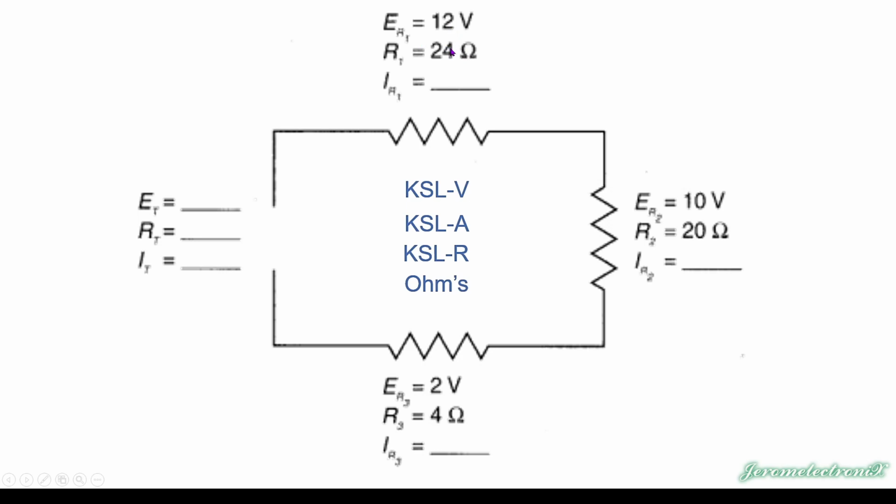Be careful. A lot of students look at this and say, oh, that's half. And that's right. But some other students think, oh, that's two 12s that live in a 24. No, that's not how to do division. The volts go in the top. The resistance goes down below. So you hit a 12, you hit the per line button for divide, and then you hit the 24, and you realize that amps are 0.5 amps.